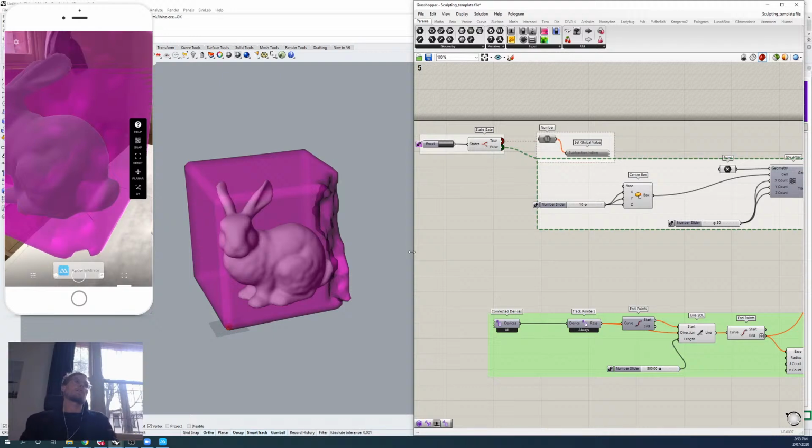Everyone probably knows what a contour is. When you have a geometry, you slice it up with different slices. Imagine you were in a room with a certain temperature, and the temperatures ranged from 0 degrees Celsius to 30 degrees Celsius. You could draw a line through the surface, like a contour, that specifies where it's 20 degrees Celsius. But because the room itself is 3D, you could easily draw an actual volume that encapsulates all of the parts that are 20 degrees Celsius. So it's like a threshold, and that's basically what isosurfacing does.